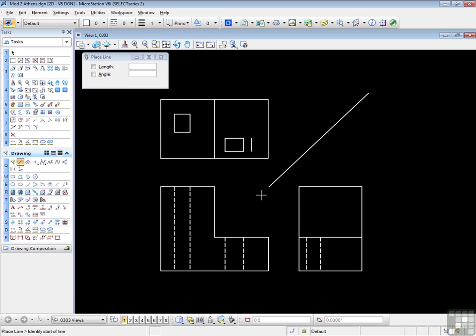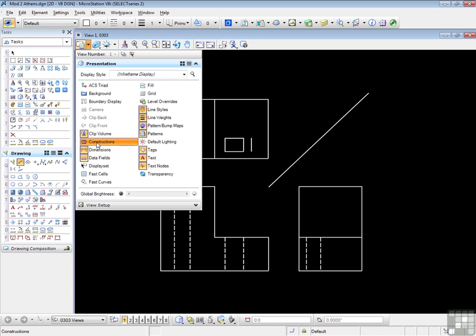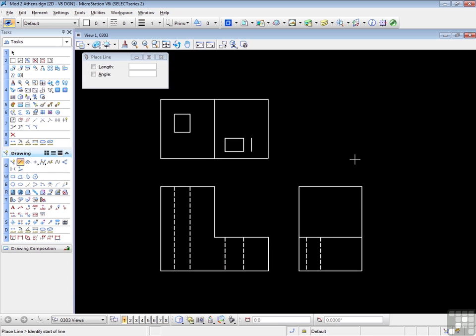There we have it. I'll leave it to you to finish off the hidden lines for the right side view here. And of course, experiment with adding your own information, or in fact, drawing your own 3-view drawings using this technique. And the last item, of course, is to turn off the diagonal line for plotting purposes. So we go to View Attributes, turn off Constructions, and our diagonal line has disappeared. Still there for future use, but now you can plot. Please experiment. This is an important technique, but remember that we'll be working with a different technique in the videos which deal with reference files.